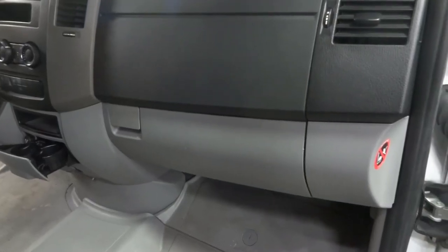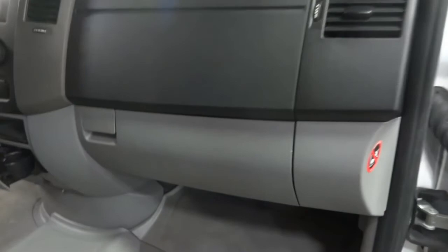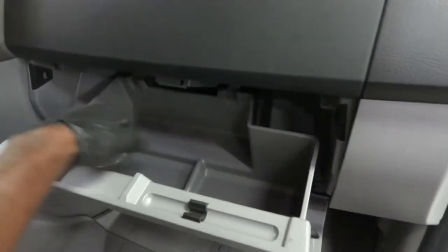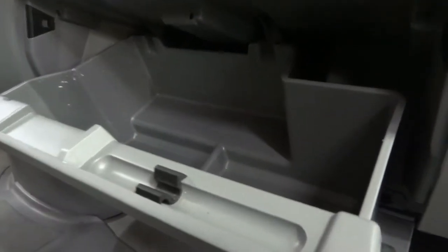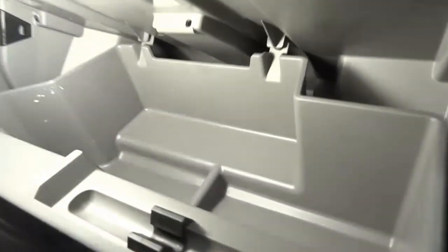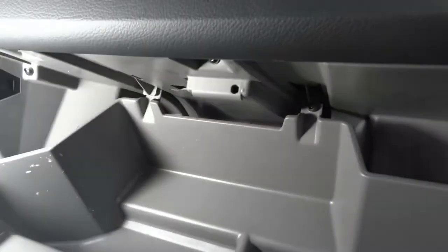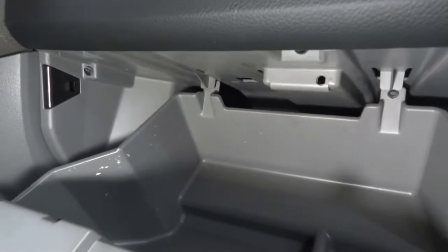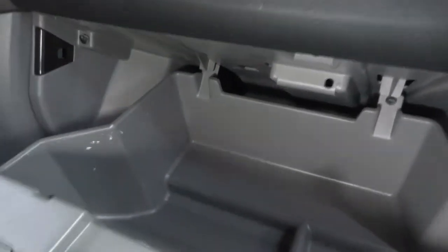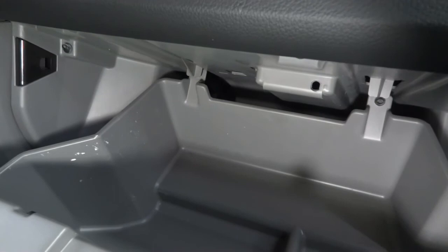Alright, so I'm here on the passenger side, and the first thing we're going to do is remove the glove box. I already emptied the glove box, so there's nothing in here. And we do have 2 tabs down over here. Let me bring in the light. Alright, so we do have 2 plastic tabs. There is this one and that one over there. So what you need to do, you just have to push them up to release the glove box. Okay, so I'm going to push that one up, and then the glove box is gonna swing down.